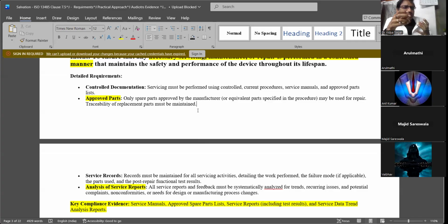So you need to have identification or traceability for that mold. Suppose instead of one mold, you have used another mold, it will lead to a different component that can't be used. So it will be a waste of time and a waste of material. So traceability of the tools that you have built in-house is very important.